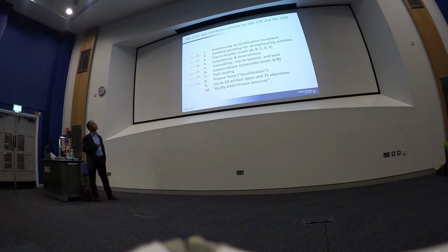Traceability, everything should be traced. This is one of the most important concepts. So you could not introduce a software that is not exactly usable for a task. Okay? So you could not load libraries that are partially used, or you could not load pieces of hardware that are not exactly used. You should use everything on board. Everything should be traced by a requirement. If you don't have a requirement, you have to remove this.